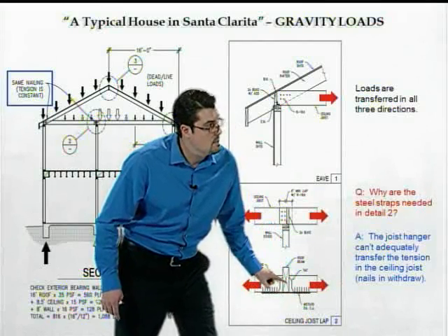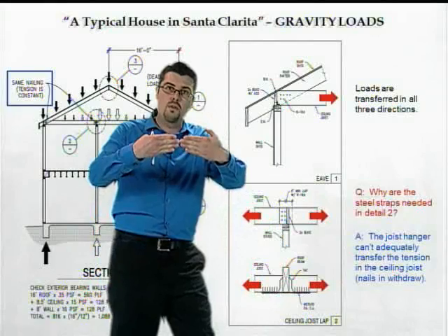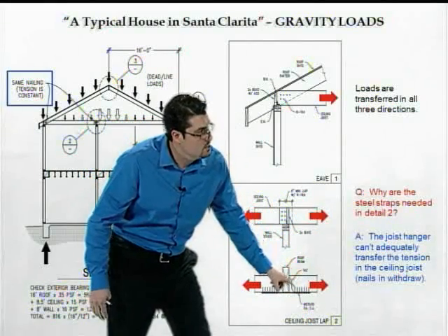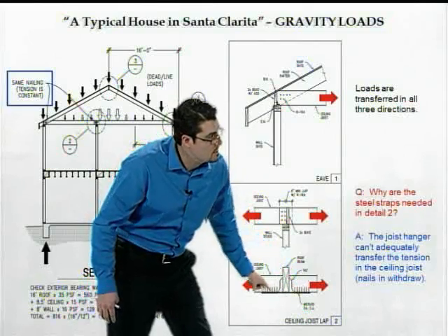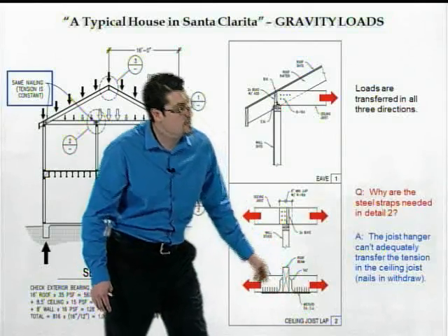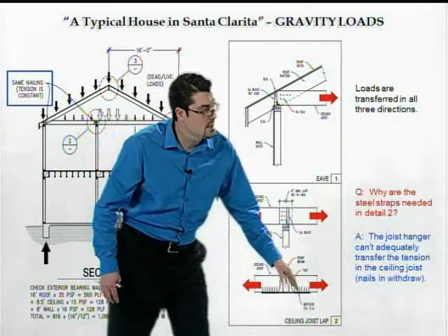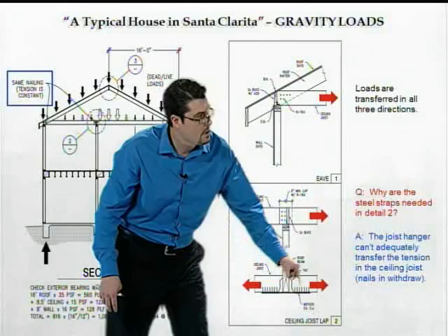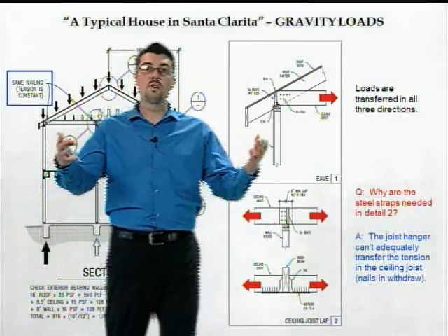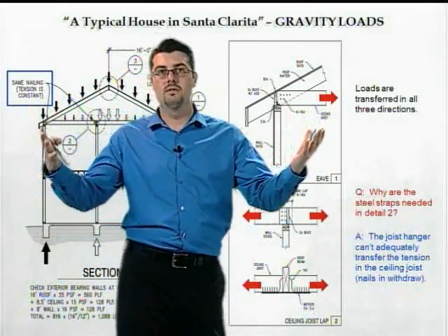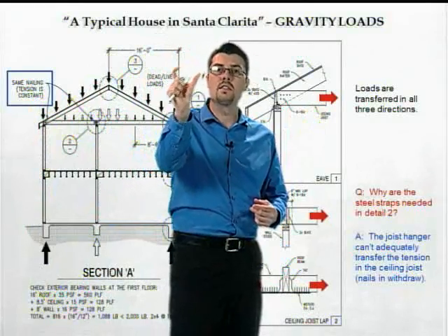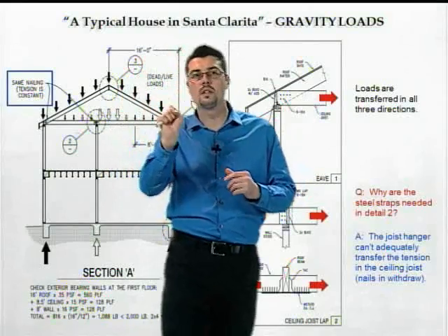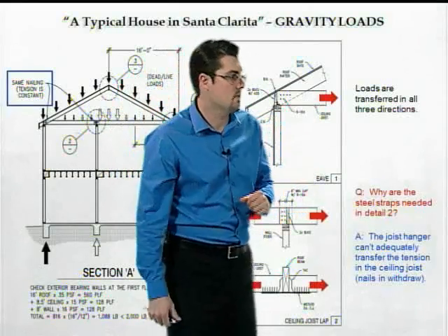When you push this beam up above, you've broken the ceiling joists. Now there's a gap. Well, to transfer that tension, you've got to give me some kind of a connection. In this case, what's normally done is they'll take a 1-inch steel strap and they'll strap right along the bottom there. Now if that strap is missing, what have you done? You've eliminated that one link in the chain. And remember, a structure is like a chain. One link missing and you've compromised the integrity of the structure.